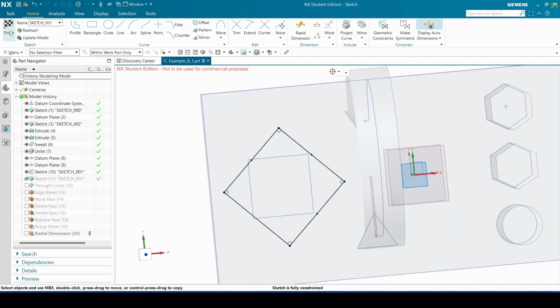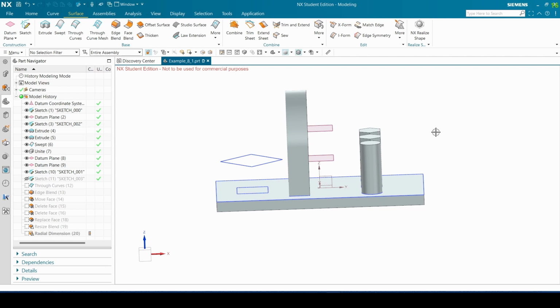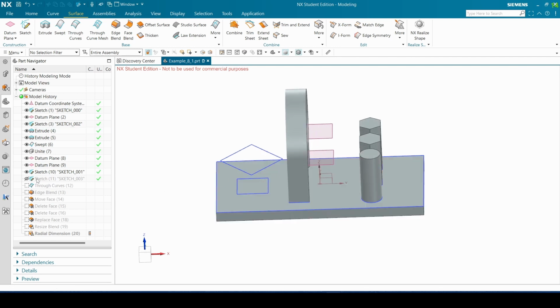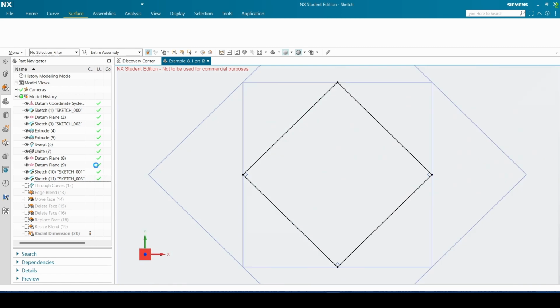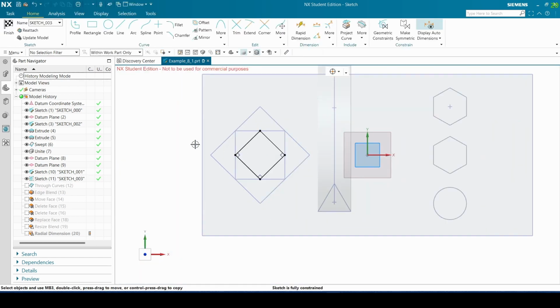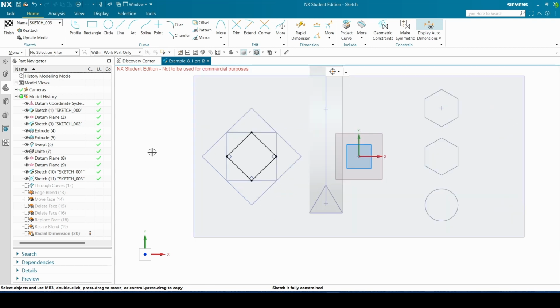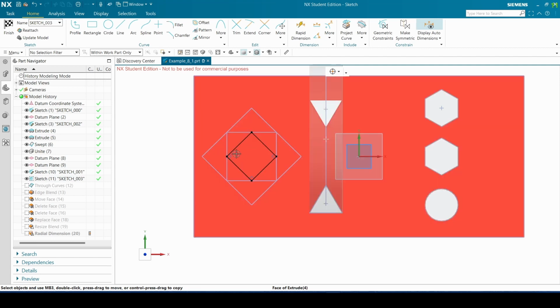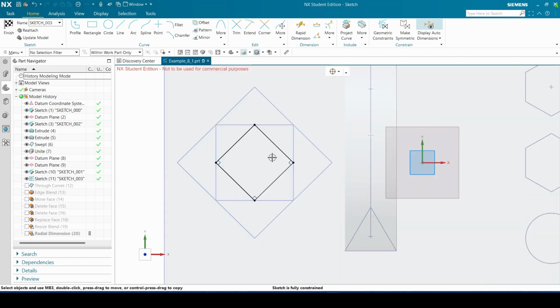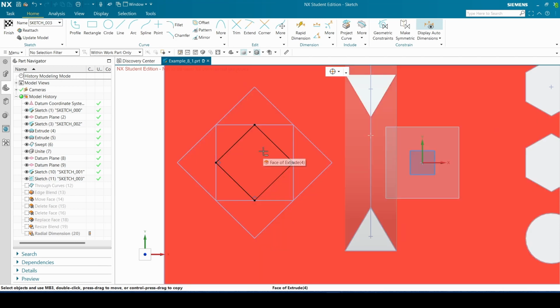You don't need actual dimensions for that. It's all constrained according to that one. And for this one, I actually didn't give dimensions. Its corners are at the middle points of the bottom square's edges. So you don't need any dimensions. You can just add them like this. A problem that you may run into is if you create a rectangle and it doesn't want to allow you to rotate it. Just check if you have any horizontal or vertical constraints on the rectangle or square, same difference.